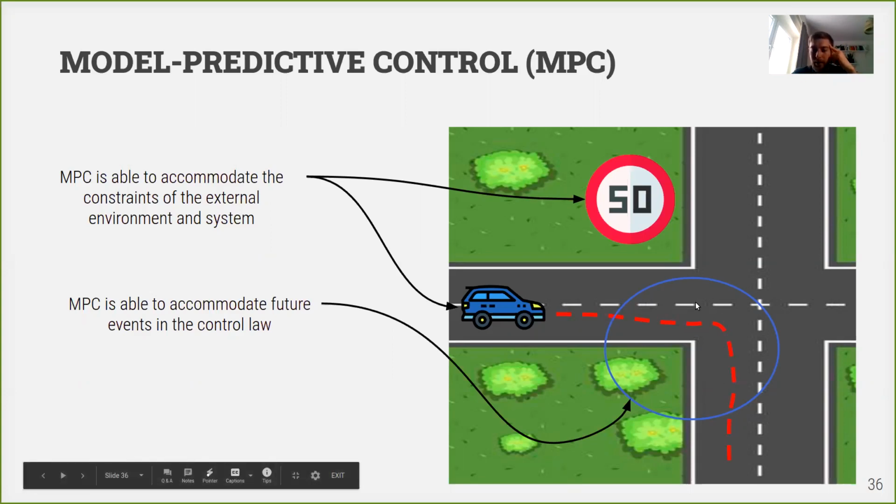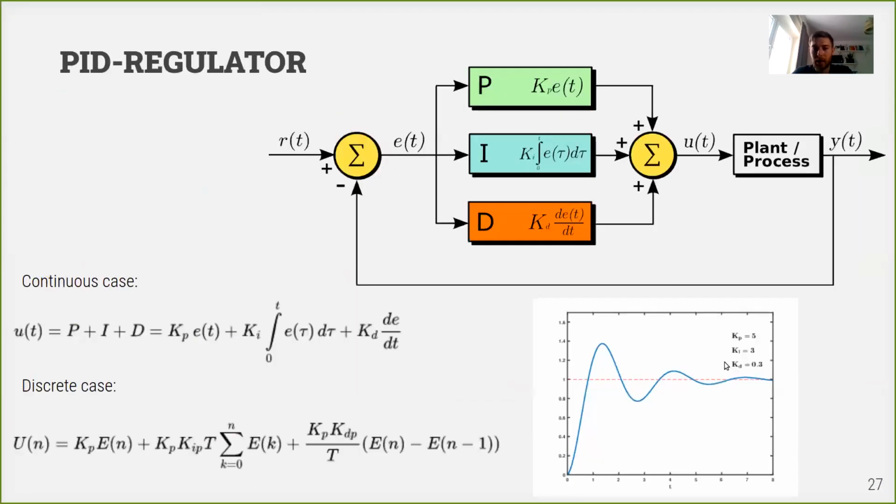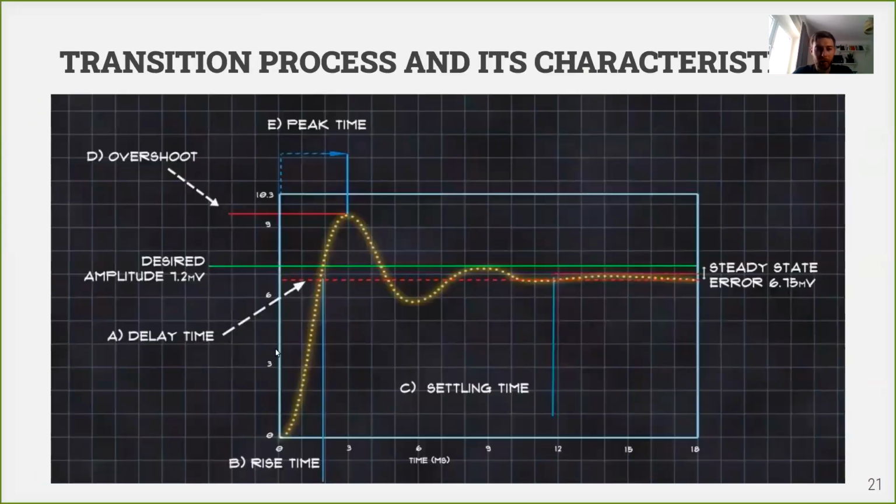So as we discussed, as you remember, our transition process will start only here. And that is why it will be really, really sharp. So from 0 angle to 90 degrees angle, we will need to turn our steering wheel really sharp. So as here, our control signal will change from 0 to 90, and with the control law, with PID-regulator, we will try to steer it as quick as possible. And of course, it will be uncomfortable.